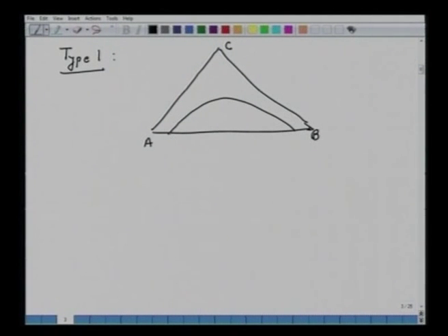This phase diagram intersects the axes A and B, let's say at L and at K. And notice there is no intersection here, no intersections anywhere. All it means is, anywhere if I choose, say, a component coordinate H, this will contain A plus B plus C. We know how to read this. We'll take the reading here, we'll take the reading here, 100 minus this will give the other component. So from this, we have A plus B plus C.